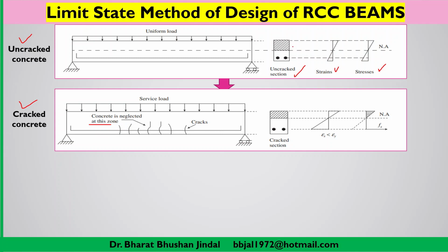Now if you compare the figure at the top and the second figure, figure number 1 and figure number 2, the effective shaded area of concrete which is taking compressive stresses has decreased comparatively. So the area has decreased. Now it is a cracked section. Earlier the whole of the concrete section below the neutral axis was also taking the stresses, but now since it has cracked, we will be ignoring the concrete below that. So that's why we are saying that in comparison to figure number 1, that is of the uncracked section, in figure number 2 the neutral axis seems to be shifting upward.